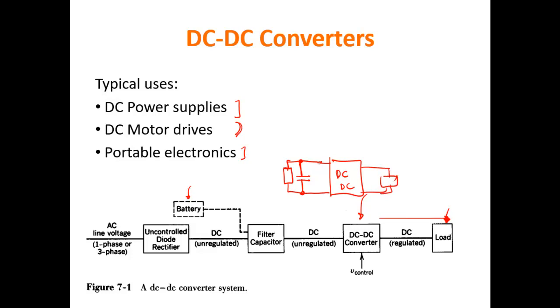So this is what we call an unregulated DC voltage, and it is not regulated because, of course, there's nothing that regulates it. The DC voltage you have here is the DC voltage that you have on the battery, which is at a maximum value around 3.8 when the battery is full, and then decreases as the battery is discharged. So it's really not regulated. There's no way to fix this voltage. You need to fix the output one, and this is what the DC-DC regulator is for.